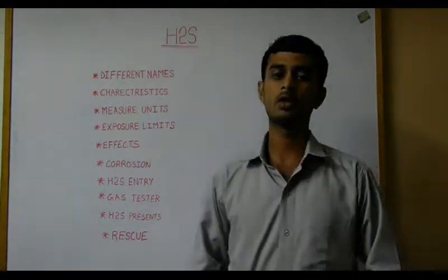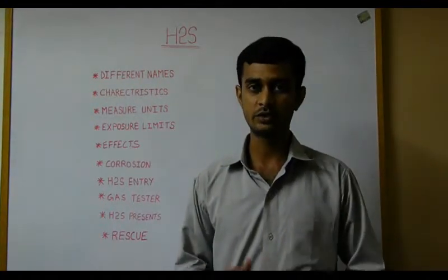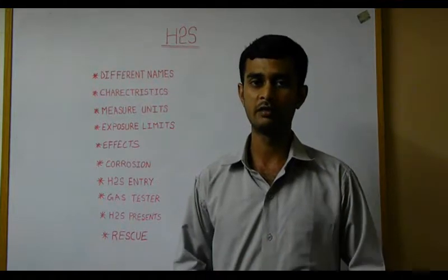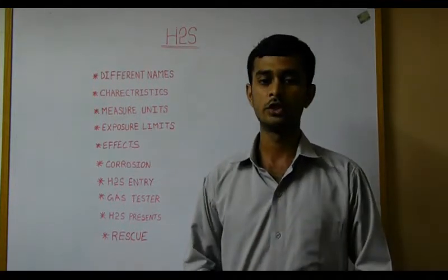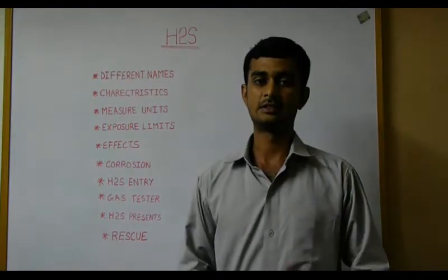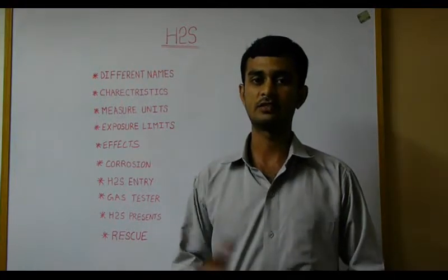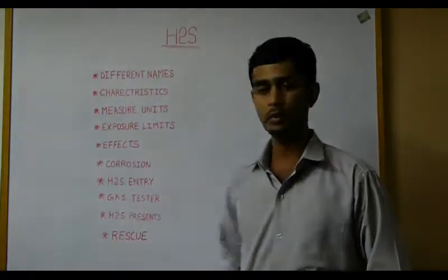Gas testers. Your gas testing device is an electronic device. It is mandatory to check for the proper working of the device before entering into the zones. You can check this gas testing device by 3 means: light signals, audible signals and vibrating signals. If these 3 occur, then the device is said to be working properly.